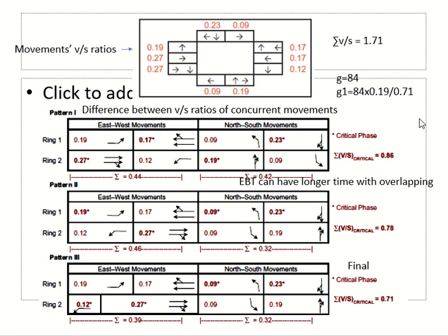Others are happening at the same time. Okay, let us take these two. I did the design for this one, right? So my signal timing is according to this movement. Okay, this one is happening together. Now what will happen? I calculated the phase time according to this. I put 0.23 here. Okay, and then I calculated for this. I put 0.19 here. Obviously the green time for this one is higher. The green time for this one is less.